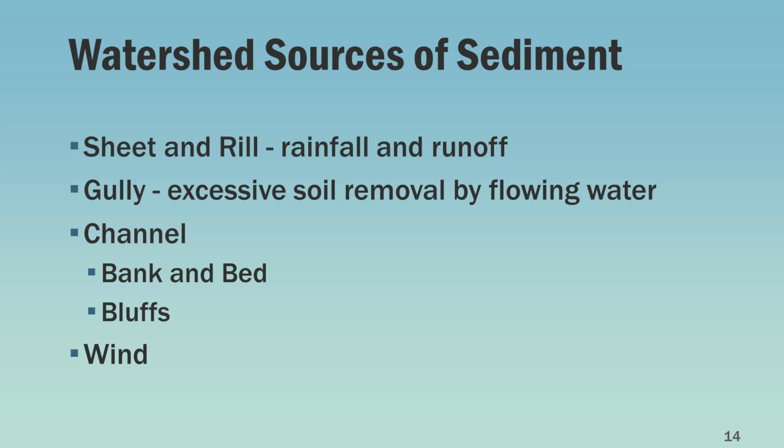Another component of channel erosion are bluffs, which I was just talking about before, where these are processes that are dependent on the composition of the soil near the banks and the soil moisture, and of course the freeze-thaw cycles, which have an impact on how much or when these blocks of soil fall into the water and then get transported.